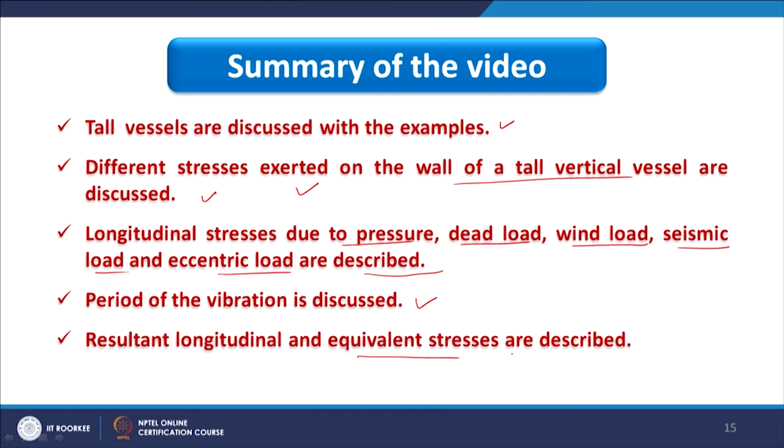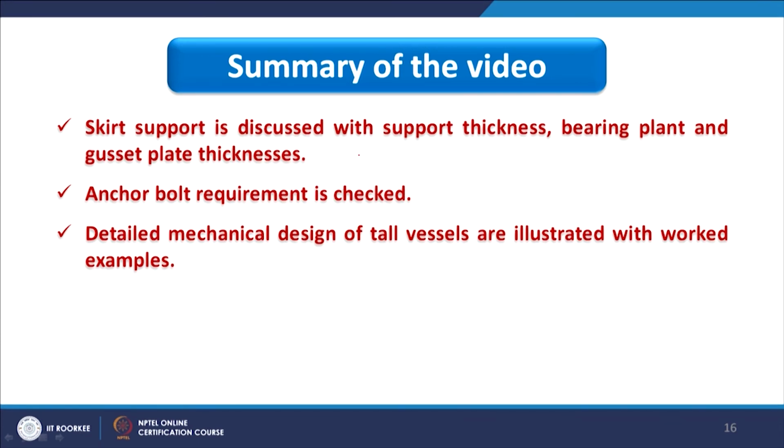Resultant longitudinal and equivalent stresses are described. And further, skirt support is discussed with support thickness, bearing plate and gusset plate thicknesses, and then we have checked whether anchor bolts are required or not, what is the condition that we have discussed. And finally, detailed mechanical design of tall vessels is illustrated with a worked example, and after that we have carried out one exercise for plate hydraulic design.